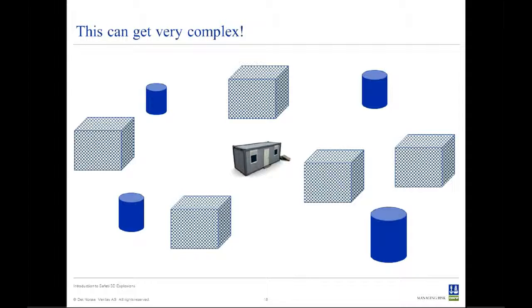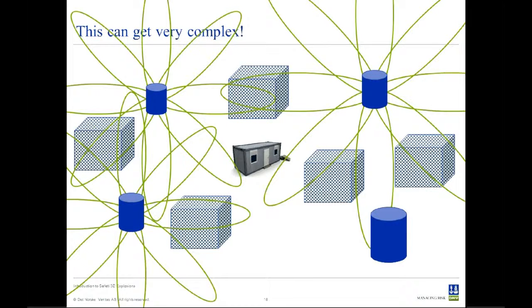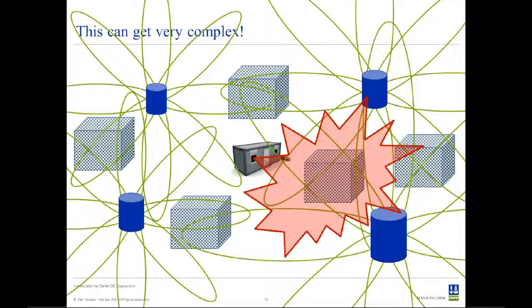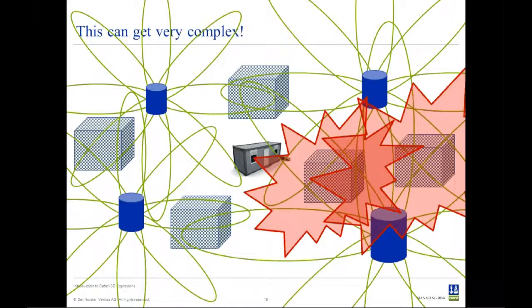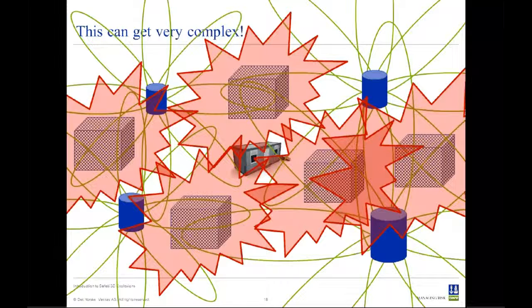We consider dispersion through all the weather directions that are possible for all of our releases, and the model needs to consider all of the potential explosion sources resulting from this arrangement, and we assess the impact from each of those explosions on the receptor, keeping a log of all of the potential interactions and impacts that give rise to damage at our point of interest.